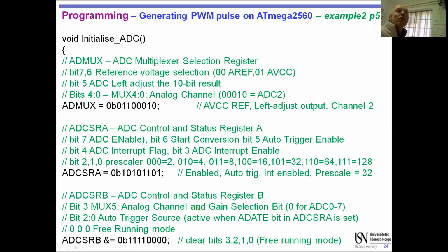Based on that value, we're going to do some maths to convert it into a position value, and we're going to move the camera. Now, the camera won't necessarily move completely smoothly because of the way we do the conversion maths. It may move in small stages rather than completely pure sweeping. It depends on how fine the maths is in terms of the small increments, and also how fast the person moves the controller. So they would need proper training to use this, because a jerky security camera is useless. You could do the stabilization in the code, or you could do it by training the operator to move it slowly. Both are useful, I would say.